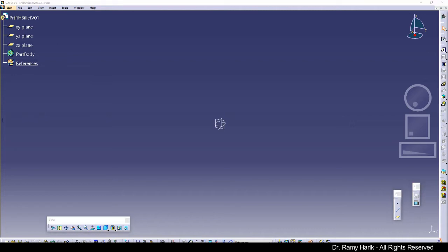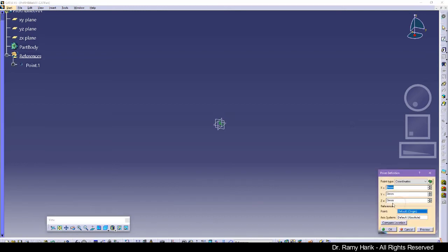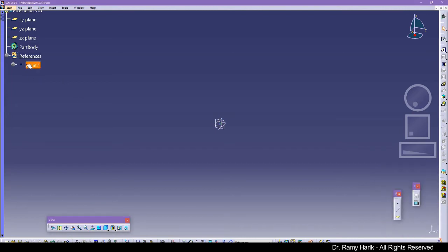It's important to connect things with respect to the different elements. What we need when it comes to prismatic is a safety plane, the tool origin, the programming origin, the machine origin, and all of these different elements. Let's start with the first one, which is the 000, and that would be our programming origin. Moving on, we're going to create the machine origin.